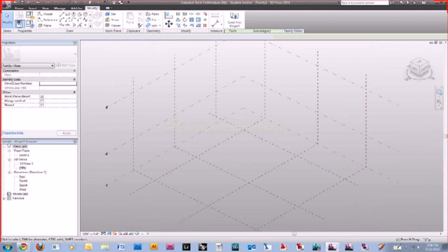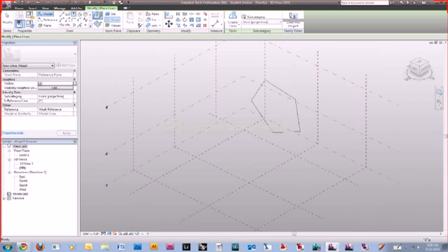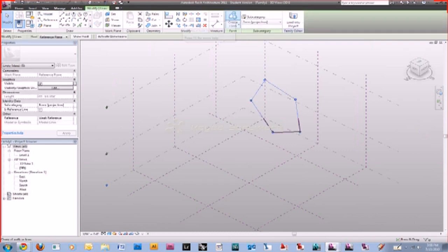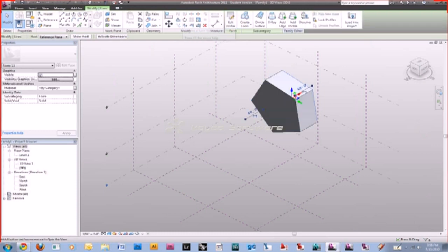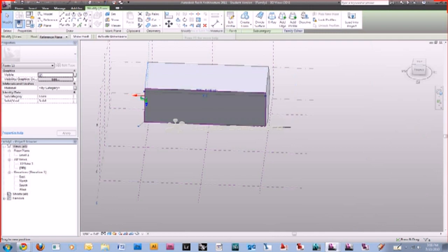You're going to draw out a shape, and much like the extrusion tool, where you would select a face and push and pull it, with the rotate command you use rotate on a face you've selected, and then you'll be able to twist whichever side you want to rotate. So let's do one of those sides. I'll do this face. Do the top, yeah.